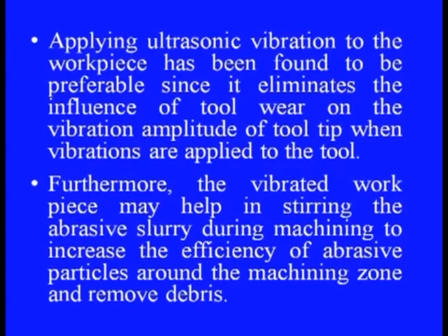Applying ultrasonic vibration to the workpiece has been found to be preferable, since it eliminates the influence of tool wear on the vibration amplitude of the tool tip when vibrations are applied to the tool. This was basically the motivation while developing the version where the ultrasonic frequency will be given to the workpiece itself instead of the tool. Here the dimensional change due to the wear of the tool will not affect the working parameters, that is the change in the amplitude of this process, and therefore, the